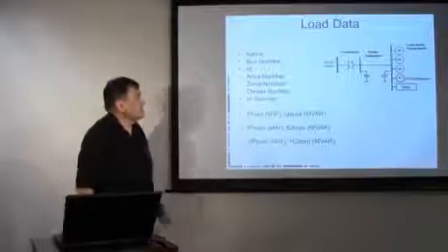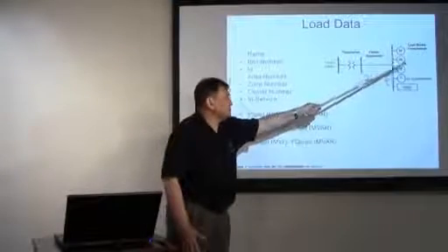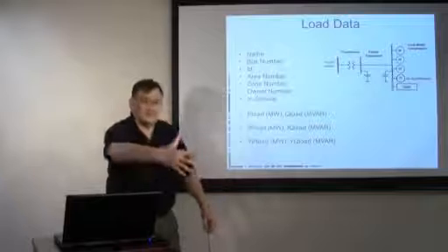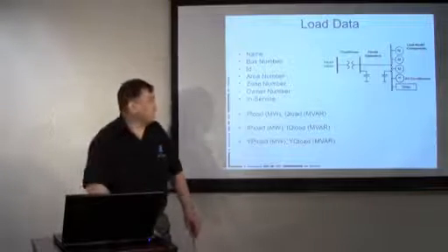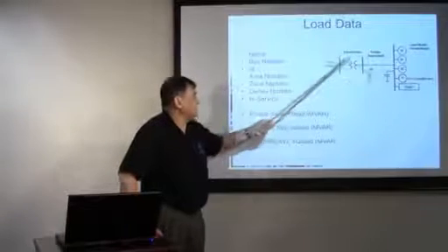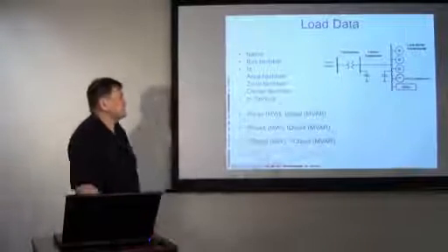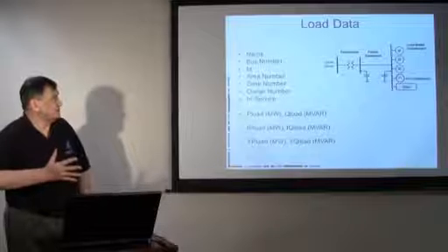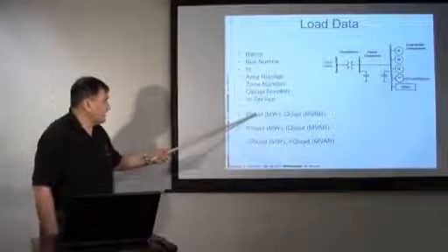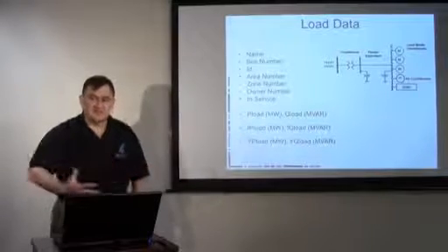What's happening, we're seeing that loads have to be modeled in a lot more detail to get the true dynamic effect. And the WECC Load Modeling Committee has said, look, we really need to model different types of induction motors of different sizes, all the way from a small refrigerator to an air conditioner to a big drive in a factory. And then we have to model the actual feeder and then the step-down transformer. But historically, we have a much simpler approach for loads. We say it's basically a megawatt and a megavar extraction from the system.